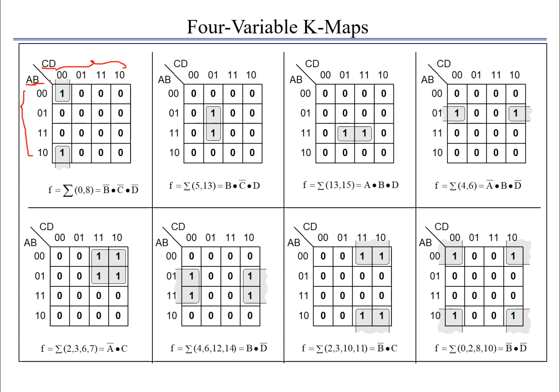When you write the first 2 bits and then the next 2 bits, it should vary with only 1 bit. See, only the second bit is varying from 0 to 1. And if you go on to the next, only the first bit is varying from 0 to 1. Similarly when you shift from 1 1 to 1 0, the second bit is varying from 1 to 0. Only 1 bit should be varied subsequently. So this helps to reduce the switching activity.